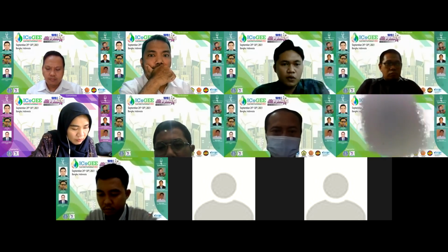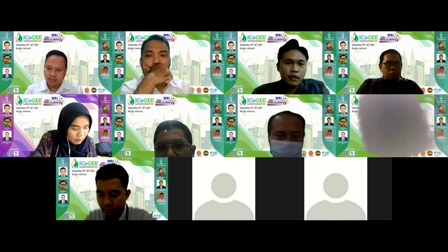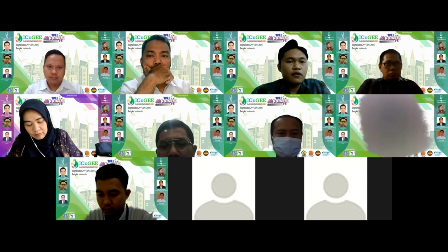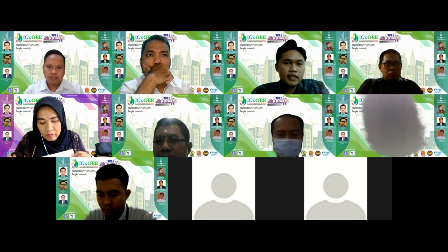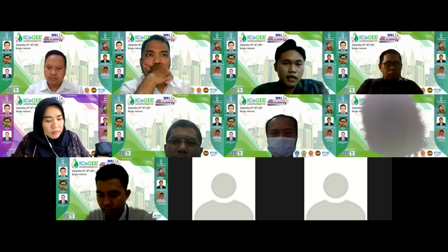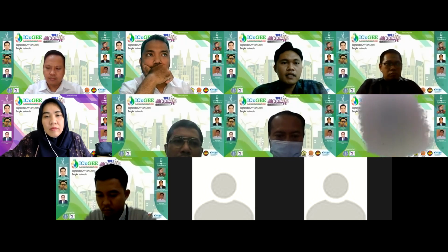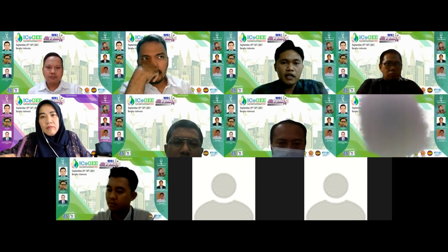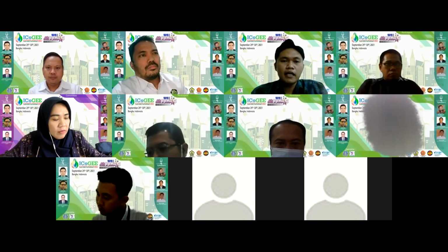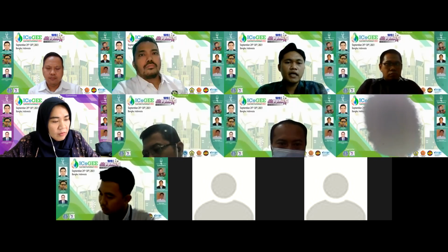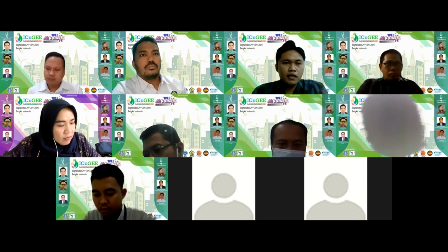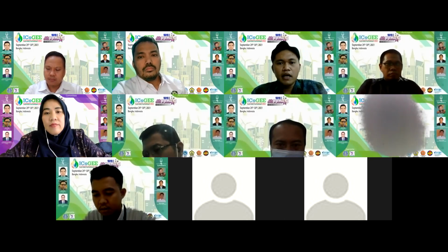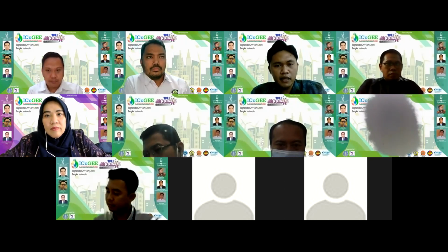In our facility, you can also come to PLTSa Bantar Gebang to see it clearly. In our facility, the grate incinerator can achieve about 1,000 degrees Celsius, and in the combustion chamber above the grate, we also manage to keep the temperature around 800 degrees Celsius, and sometimes it can be 850 degrees Celsius.